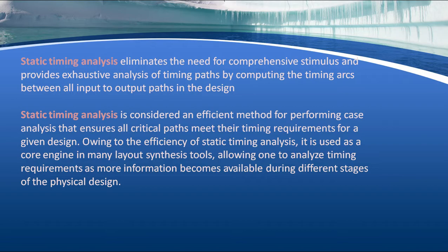See, static timing analysis is considered an efficient method for performing case analysis that ensures all critical paths meet their timing requirement for a given design. Owing to the efficiency of static timing analysis, it is used as a core engine in many layout synthesis tools, allowing one to analyze timing requirements as more information becomes available during different stages of physical design. It's one of the fantastic tools to not only lay down better performance of a circuit, but also a robust design we will get from static timing analysis.